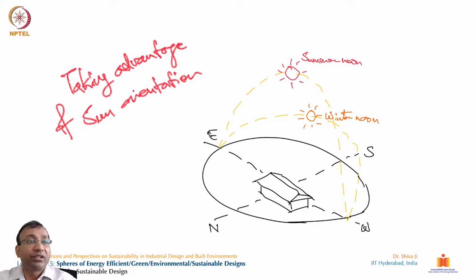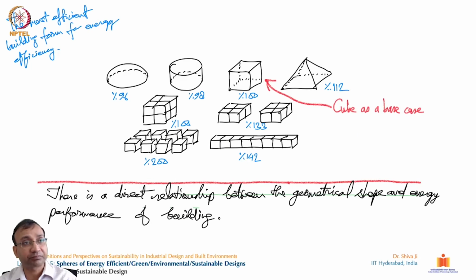So this is one sketch, you may have already seen it. With the location, like a latitude and longitude, we can optimize the efficiency of the design by changing the orientation, the form, the overall volume, and the materials coming from that particular direction, depending on whether we need heating or cooling. Depending upon that, we can choose facilitating materials, insulator materials, or conventional materials.